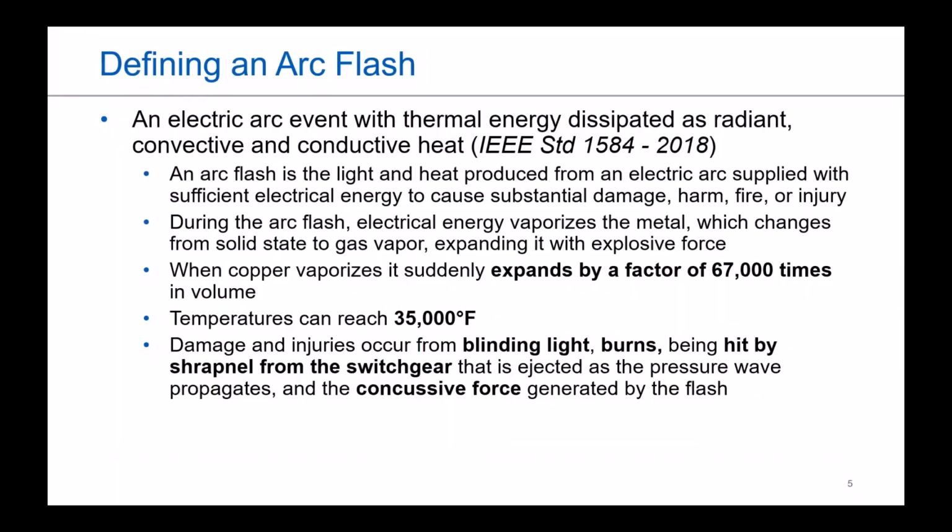So the first part is really want to dive into why this is a big ordeal and why this is important for people to have in the front of their minds when they're either looking at older installations that they may be replacing or just doing straight new installations from the start. Particularly as transformers themselves become more and more efficient, you have a higher likelihood of increased current available in the secondary, which then leads to higher incident energy levels available with the equipment. And with that, there's a higher level of risk.